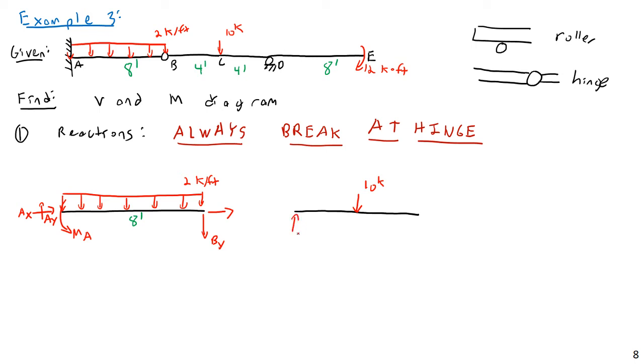And let's just assume, then, BY here like this, and then a BX and a BX like this. So when I cut the pin, I reveal 2 internal forces. Notice there's not going to be any internal moment revealed because it is a pin, but there will be internal X and Y forces revealed. I can assume there's an upward force here and a downward force here, or the reverse, but it is absolutely essential that I assume compatible loadings. If I don't, I'm going to get it wrong.